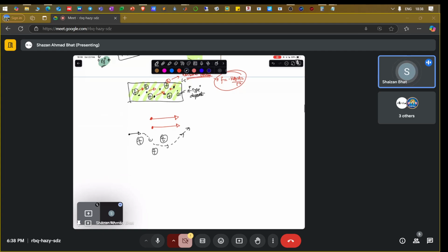That is how the electron tries to move. This is called scattering, and particularly it is called impurity scattering, because these dopants are impurity atoms. That's why it's called doping, because they make the pure sample impure by introducing these scatterers, these doping agents.